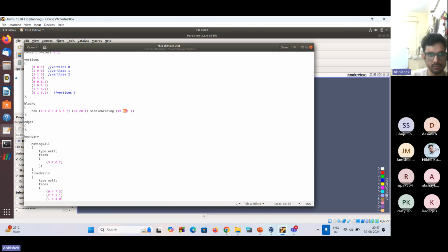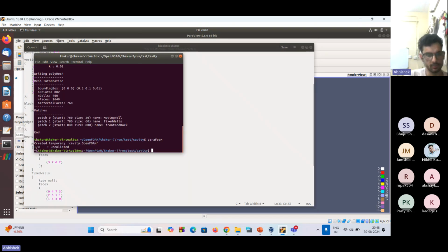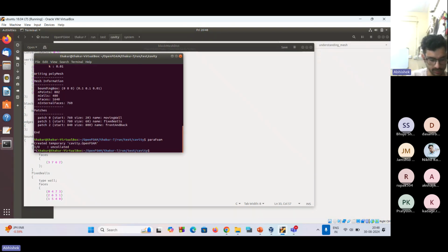This is used very much when we have flow through a channel or flow through a pipe, where you want a smaller mesh size near the boundary layer to resolve the boundary layer. And this is very important in turbulent flow, where we want to resolve every eddy that you have near the wall.